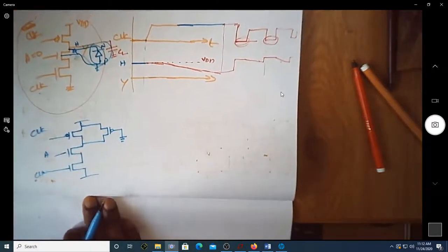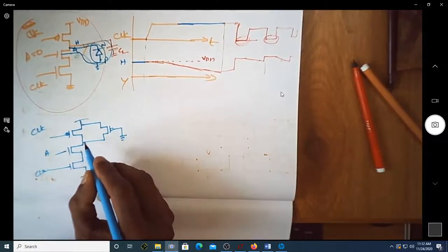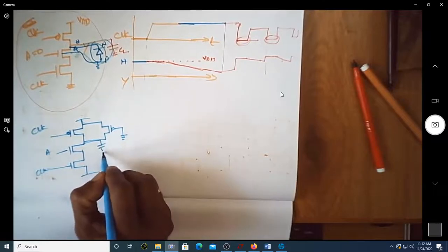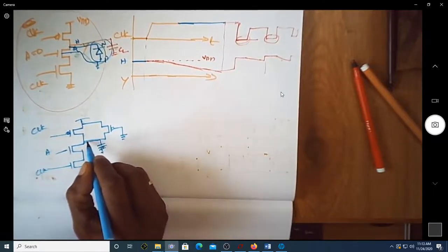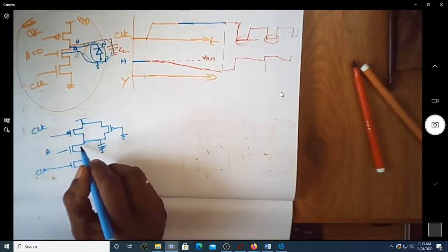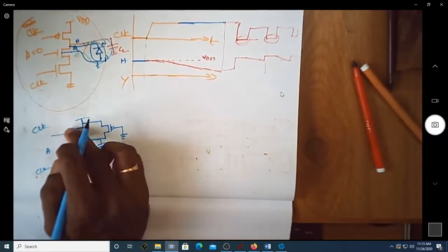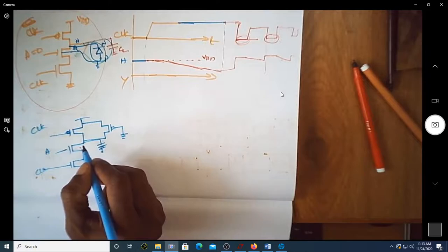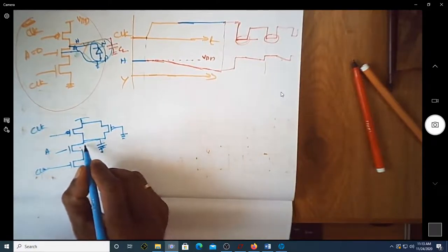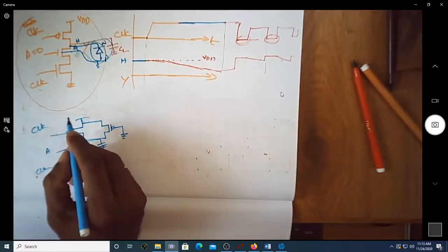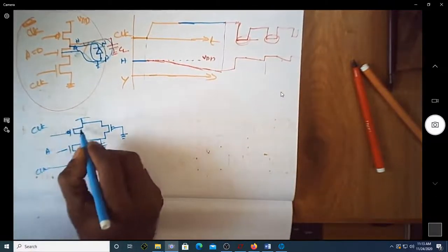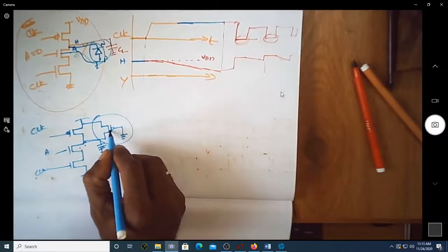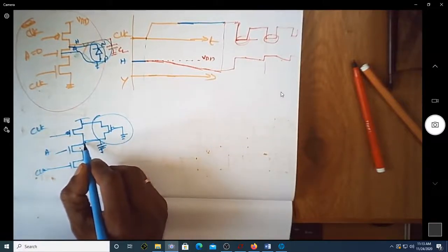See now what are the advantages here. There was a possibility of output voltage that is stored here. The charges that are stored in this output capacitor were getting leaked here. When it was getting leaked, you are supposed to pre-charge all the time using this transistor. But if you can see here, this leakage will come into the picture only when the output voltage is high. If the output voltage is high, since you are in the evaluation mode, there is no path for this to get the charge. So you provide an extra path through this transistor to ensure that this is made equal to VDD.